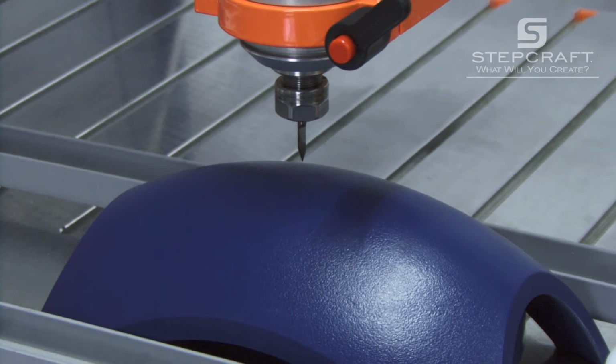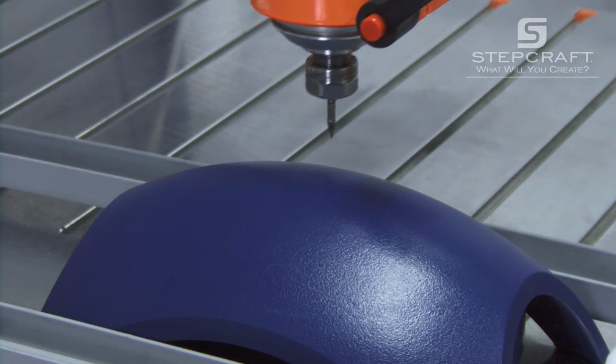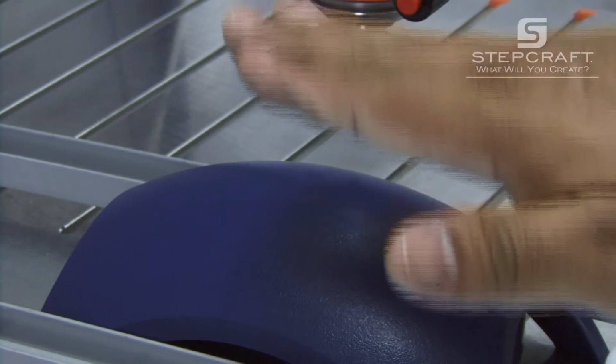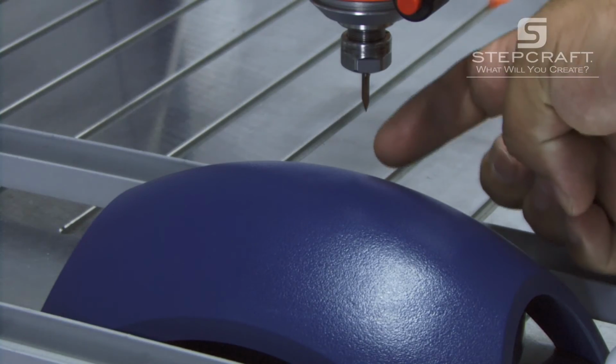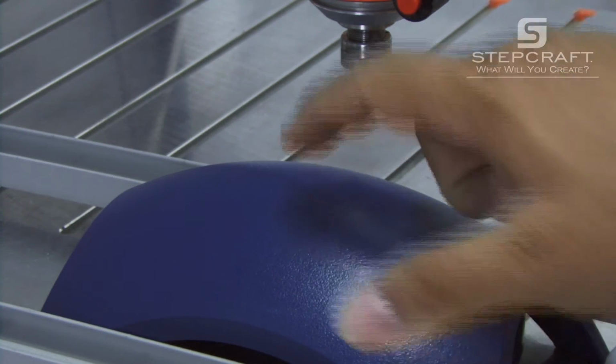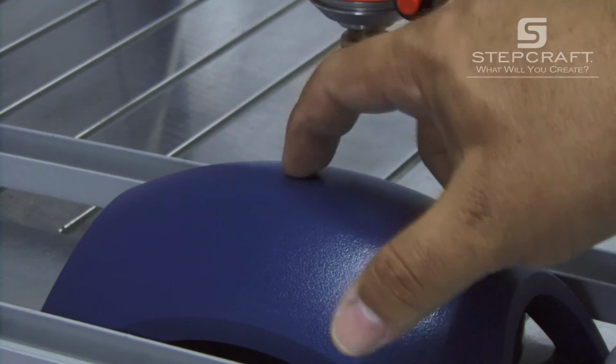Now we're going to make those 5 millimeters down for the C. I'm going to put the end mill here, so I lower the end mill 5 millimeters, then put the 0 for the C only, move it to the 0, and it's going to be here, right on top.